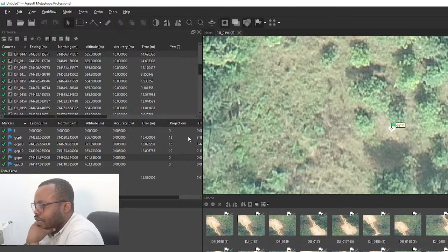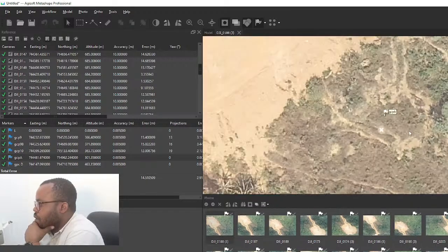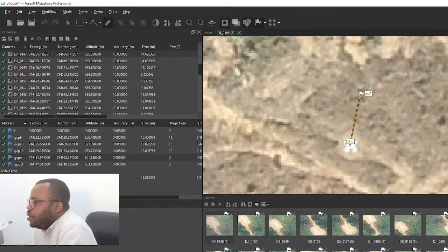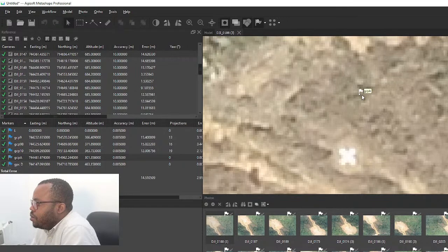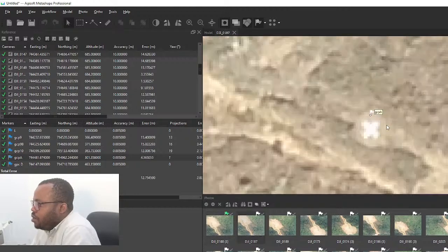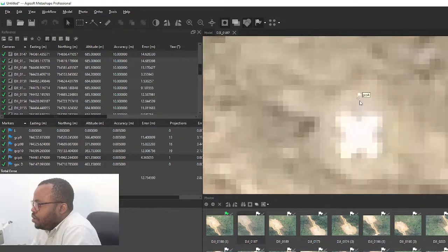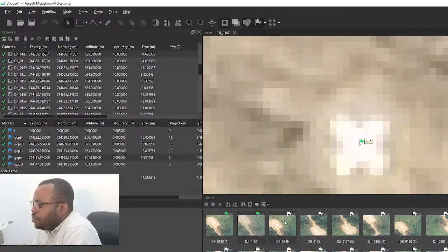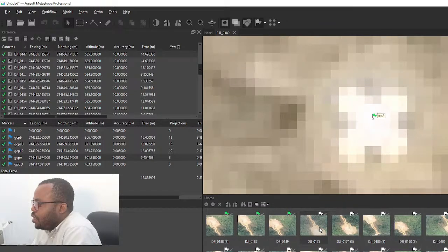I have done that as well. You can see that this is also off, so let's check by how many meters, which is always a good reference. It's about 3.6 meters off, so we need to correct that. We push the marker, or the point, onto the marker, and let's hope. You see it's converging, it's getting closer. Let me check the distance. That's about 80.5 centimeters, so we're getting there. Let me correct it. Now you can see the rest are converging.